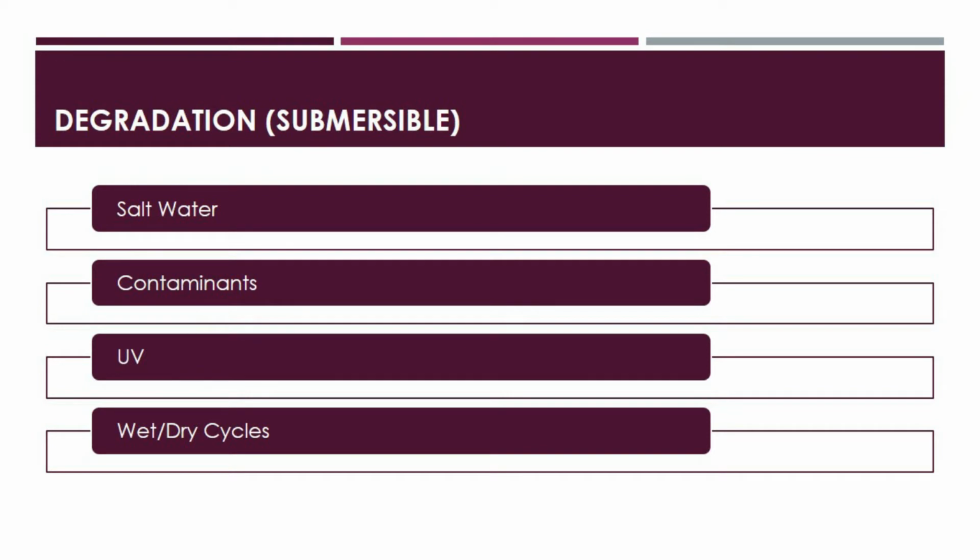Switchgear degradation can also be caused by electrical stresses. Currents introduced that are higher than the switchgear's rated current will add to a higher risk of degradation and failure. Insulation failure and flashover can both be caused by electrical discharges or surges. Electrical discharges in oil or SF6 might cause contaminants to form in the switchgear unit, causing it to degrade.